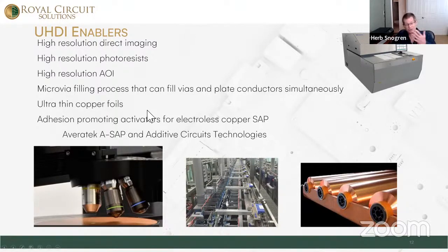Now you can buy commercially copper foils that are 1.5 micron to 3 microns thick. These weren't available years ago, and what companies were doing was etching down 1/2 ounce copper or 1/8 ounce copper to thinner foil thicknesses. And now you don't have to do that. You can just buy some off the shelf thin copper.